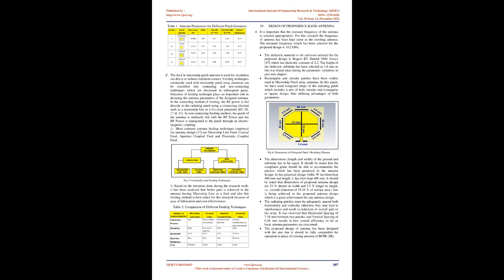4 geometries of patches have been studied and results obtained after simulation for the same material, RT Duroid 5880, for the substrate, and the same dimensions of substrate and ground. The maximum, or best, values of return loss and VSWR have been for the octagonal geometry.